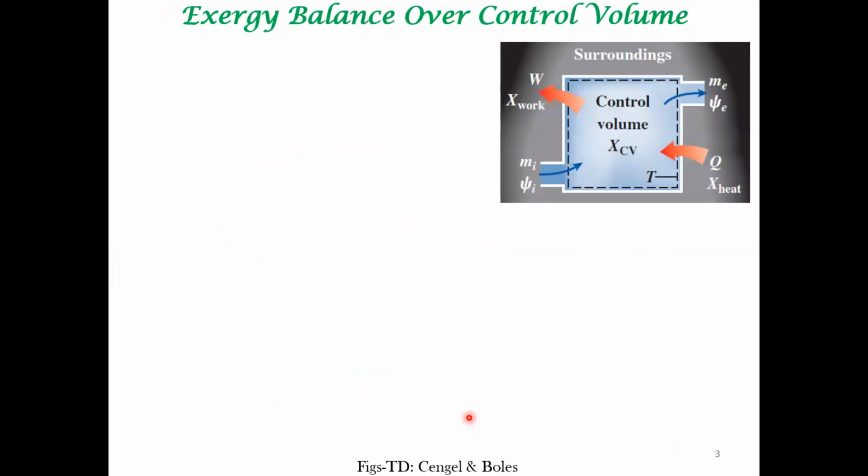In this lecture, we will look at Exergy balance over control volume. Compared to a closed system, which is most amenable for analysis, control volume systems are what you see in a typical engineering system. Here, not only can there be work interactions and heat interactions, but mass can also flow into the system and out of the system. Associated with unit mass, you can associate Exergy.